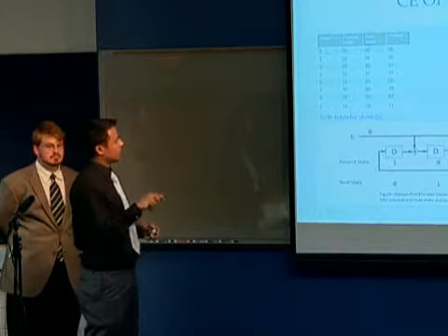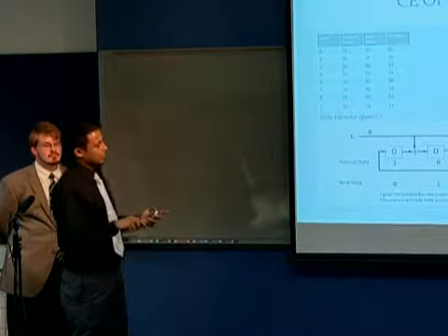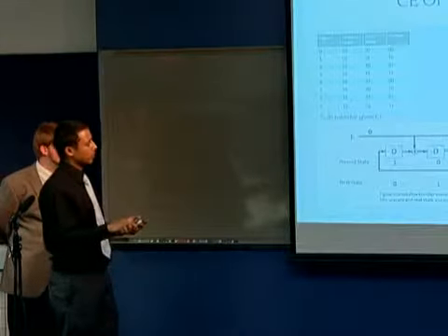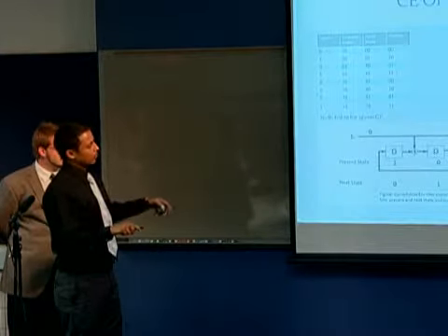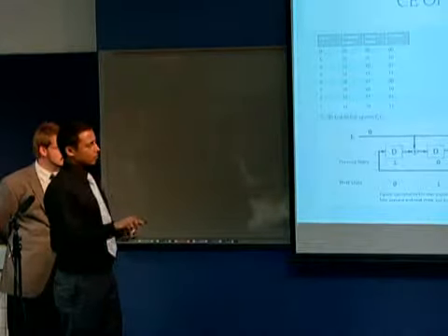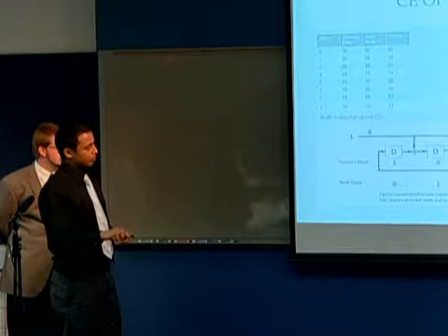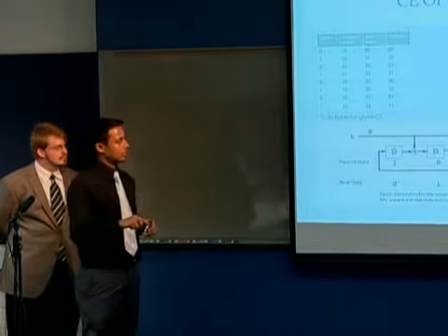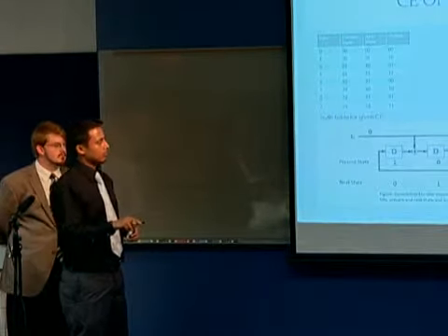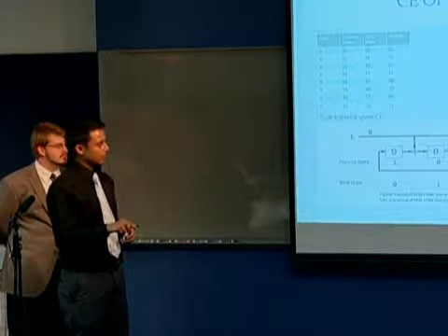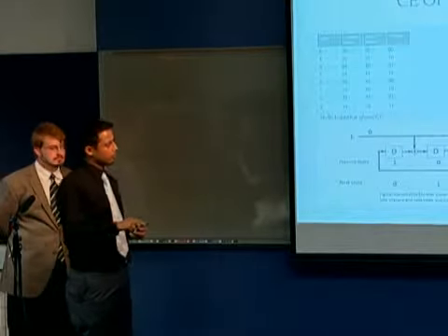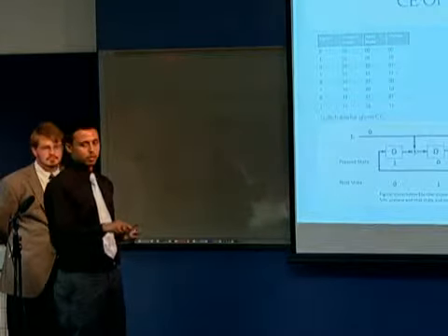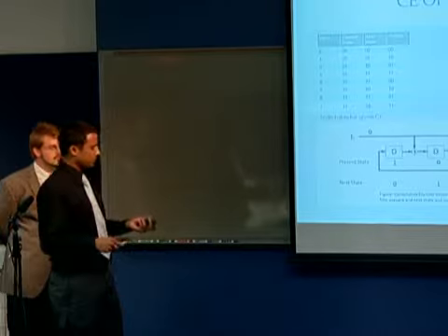So we made a truth table out of that, and that's basically what the trellis is. You have a convolution encoder at state 0, you receive the input of 0, so it goes to 0. Each transition on this trellis is a partition. So when it goes from 0 to 0, it outputs W1. When it goes from 0 to 1, it outputs X1. So that's how it works.